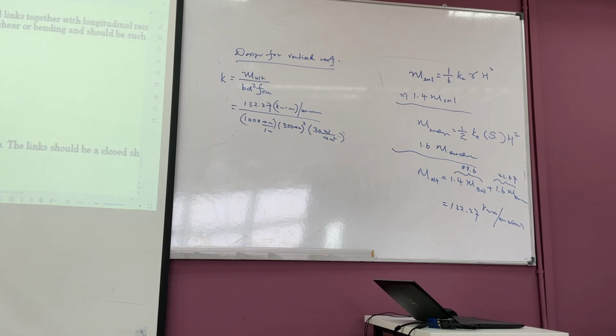This thickness here, let's say is 400, right? We have this moment here, and that is why the rebar is going to be like this. So D is from here to here, which is less than 400. So I give it, let's say 300. Understand? D is the effective depth.